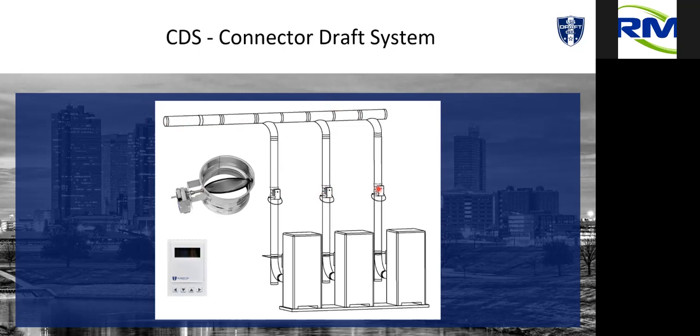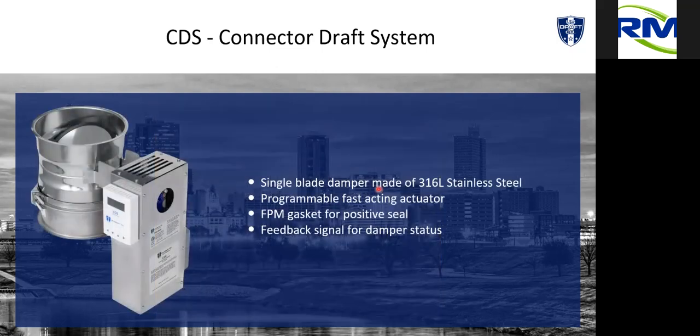And again, this is where the primary secondary mentality came in, that if you had multiple boilers needing multiple flow rates, you would just put a primary pump on each boiler to give it exactly what it wants, and it would modulate based on the newer technologies. You can actually vary flow into the boiler. That's exactly what we're doing here, is modulating at the appliance where it matters to maintain that efficiency, maintain that consistency. And after we released this actually started becoming one of our more popular products, because it can be used in so many different applications.